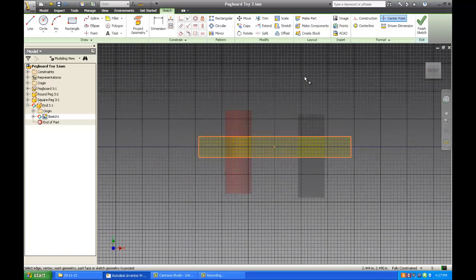And now I'm going to want to draw on a pegboard, or an end, I'm sorry. So use my line tool. I'll start on the line, go straight up, 90-degree angle out, 90 degrees down, 90 degrees back over. Notice that when I get to a point that's lined up with the top, you can see a dotted green line. That's good. So I'll click that and I'll go straight up. As you can see, it's now drawn from edge all the way over to edge.